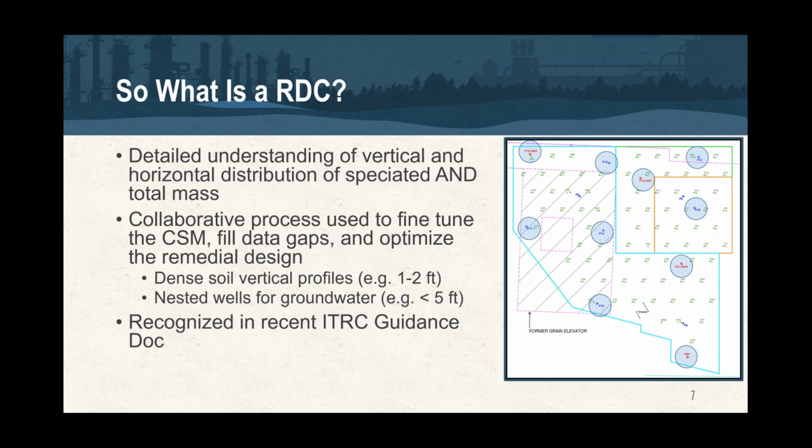From a groundwater perspective, if we've got a 20-foot screen, we want to break that down into, let's say, you can use a hydro punch tool, or you could set nested wells to get some vertical delineation with groundwater as well. And this process is recognized in the recent ITRC guidance document. If you need a link for that, please let me know.